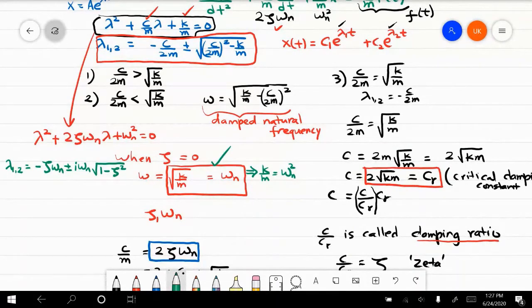So in this way, the real part of lambda is minus zeta times omega n, and again this is represented by eta, and this eta, as we have already talked, okay, this governs the decay rate of the amplitude. Okay, so what did I say when we were talking about the second case? We said that there is a real part and then there is an imaginary part. The real part controls the rate of decay and the imaginary part controls the frequency of oscillation, right?